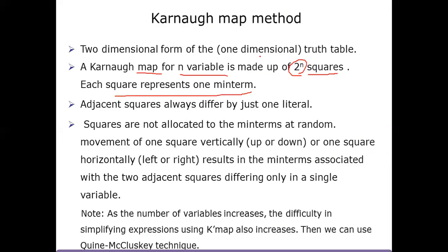If you consider two variables, you get the product, and the variables are primed when the value is 0. So that's the rule. Keep that in mind. Remember what a min term is. It's really important and required to understand this process. What's a min term? It's the product of the variables, and a variable is primed only if its value is 0. If a value is 1, it's not primed. That's the definition.